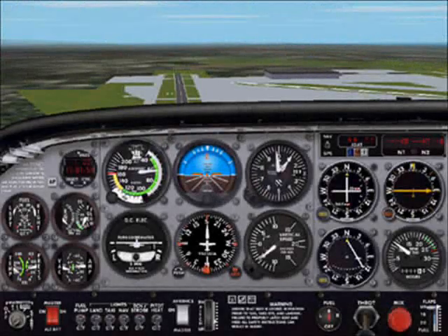While approaching without flaps at 65 knots, let's assume we notice that the runway is disappearing below the top of the airplane's panel as shown in this picture. This is one cue that you're going to be too high on the approach. Now is the time to add flaps, or more flaps. You'll press F7 once to lower 10 degrees of flaps. You'll also have to apply a little forward pressure to correct the flap-induced pitch up, and then readjust the pitch for a final approach speed of 53 knots.